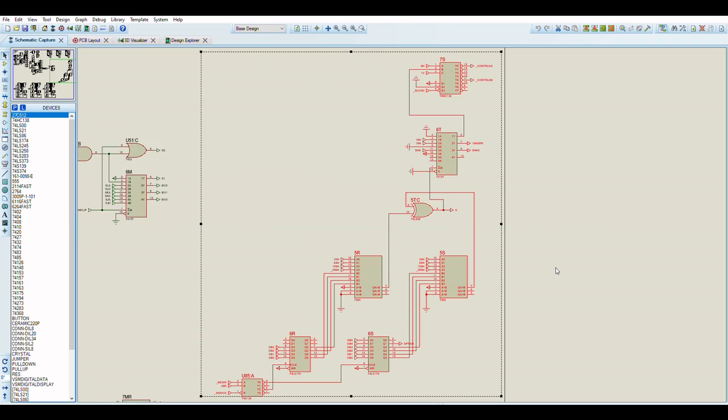This logic here deals with configuring the hardware to render or start rendering 32 by 32 pixel sprites. So the original BombJack hardware had a really neat feature where you could start rendering 32 by 32 pixel sprites instead of the normal 16 by 16.